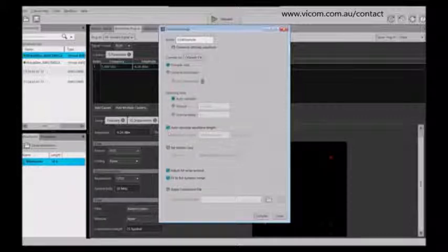You can have it auto-calculate the waveform length, and this is dependent, again, on the characteristics of your generation tool. In most cases, you want to leave this automatic. So if you're creating a PRBS type waveform, it's going to calculate the length of the waveform to make sure that it fulfills that PRBS requirement that you've set.